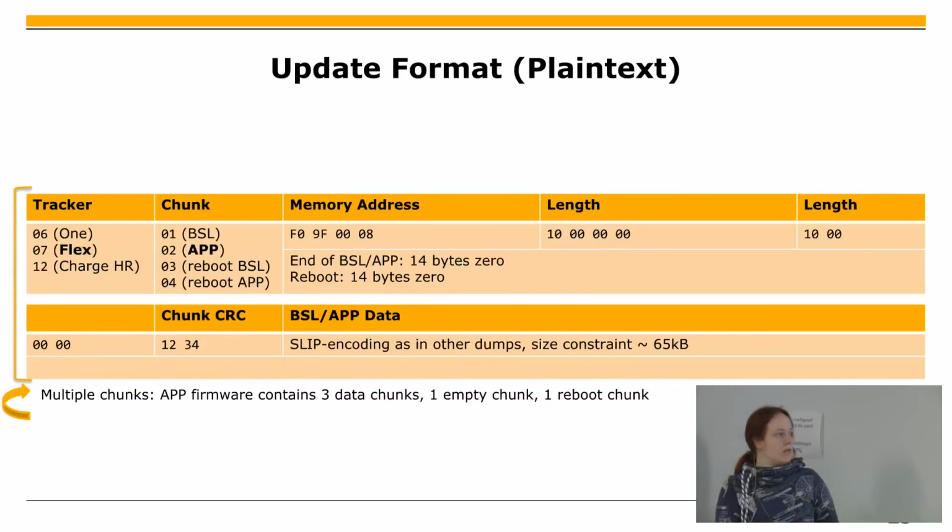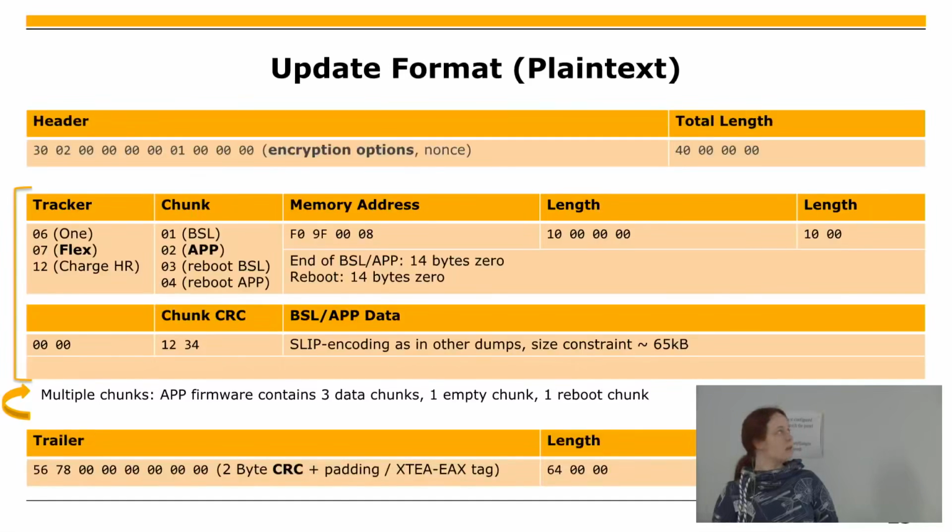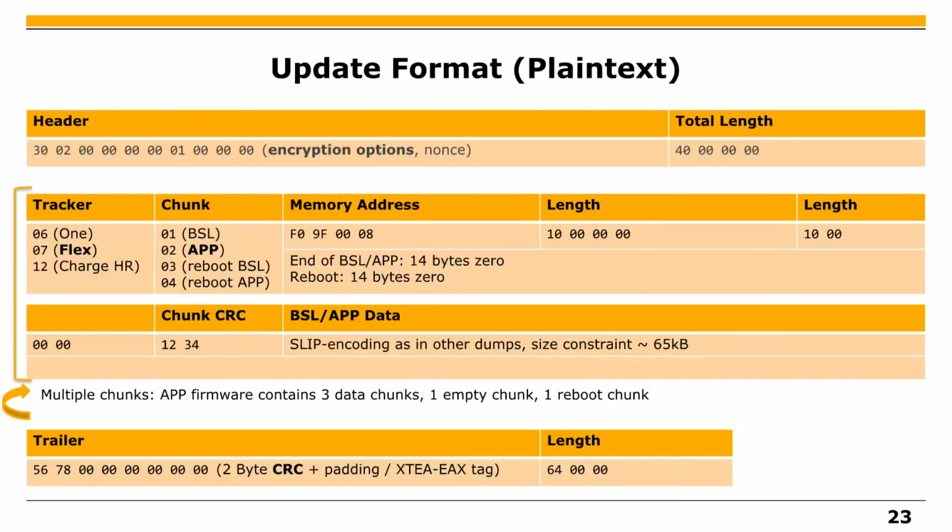And then you have one empty chunk to say it's finished, and then one reboot chunk, which is then rebooting this thing into the app. And this complete thing again has a header and a trailer. The header tells you if it's encrypted or not, has again a length field for the firmware, but also the frame has a length field here.